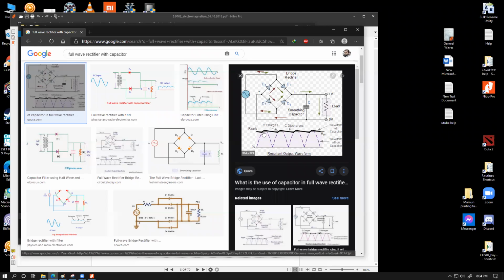So sir, what basically, roughly, the way it helps is that it reduces the amount of variation of voltage fed to the load. I mean, if the capacitor did not exist, the voltage across the load would vary the whole cycle value, maximum over here, zero over here. Introducing the capacitor enables us to reduce the variation.